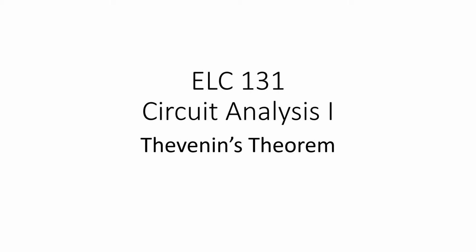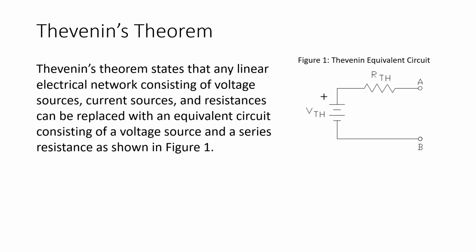So this is ELC131, Circuit Analysis 1, and the topic of this video is Thevenin's theorem. Thevenin's theorem states that any linear electrical network consisting of voltage sources, current sources, and resistances can be replaced with an equivalent circuit consisting of a voltage source and a series resistance, as shown in the circuit of Figure 1.